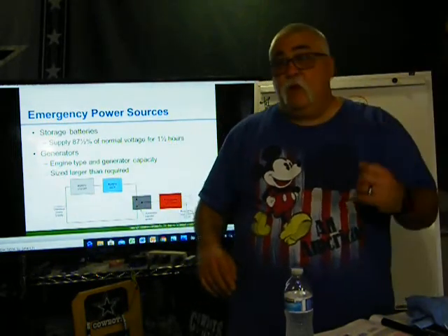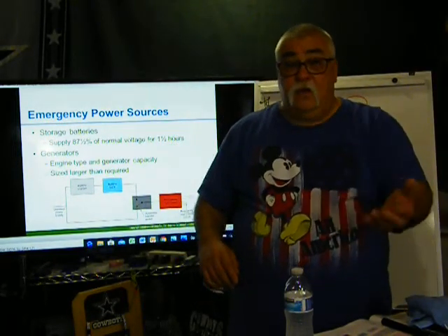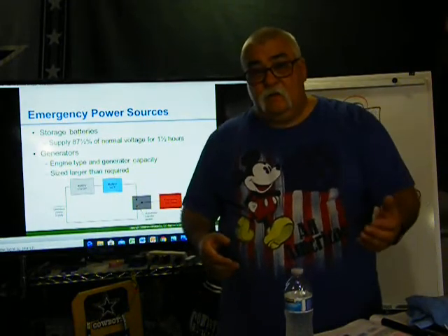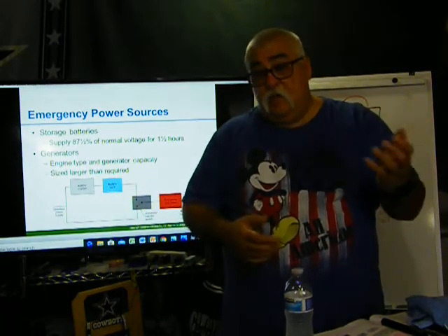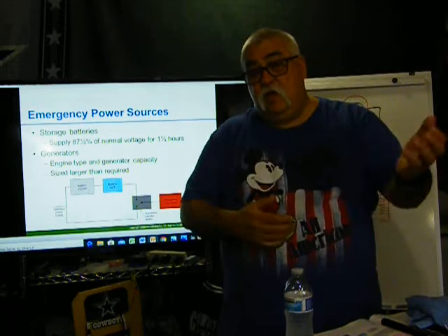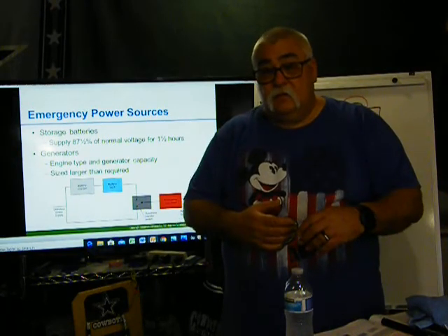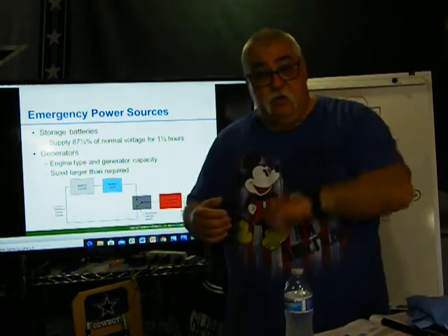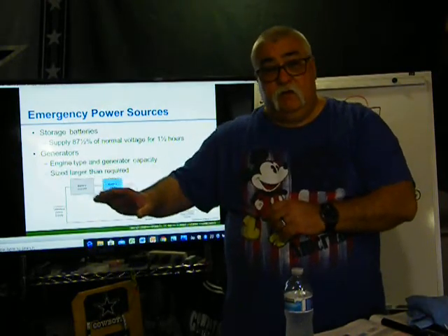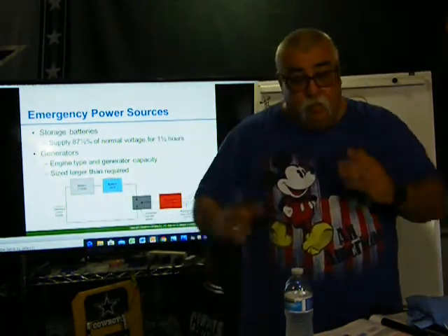So let's say the main breaker goes bad, and you don't have a 400 amp main breaker on hand. Or consider the time it's going to take to change out the disconnect, because it's not fuses, it's a disconnect. So you have a separate service that you can transfer over to, turning power over to the other side. Now you can work on the other one. That allows you to do that.